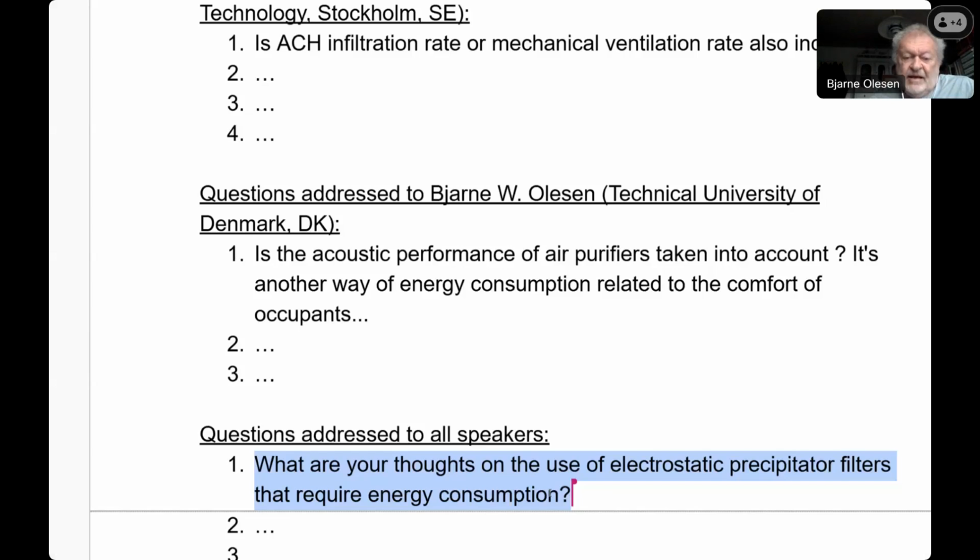We also have to be careful that you check if any ozone is generated, because ozone is very reactive and will react when it comes into the space with human bioeffluents, and we see new substances generated which people find very annoying. That's why we have seen that some air cleaners make the air worse than without the air cleaner.